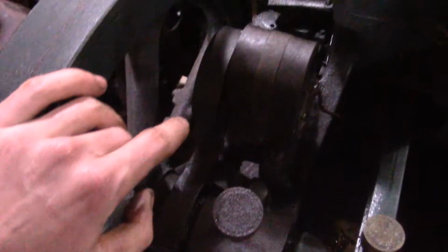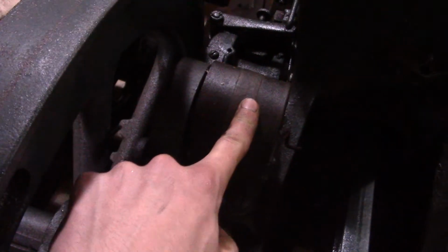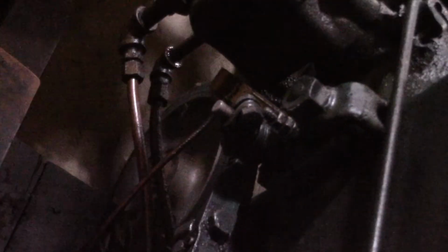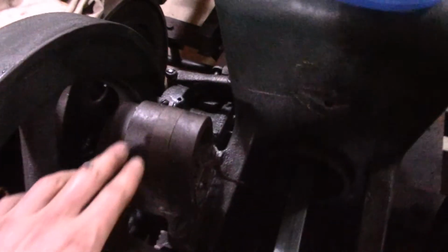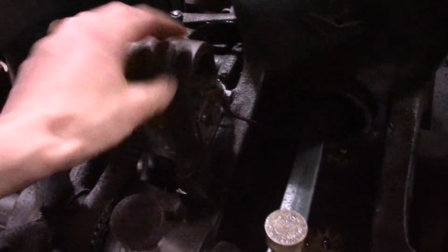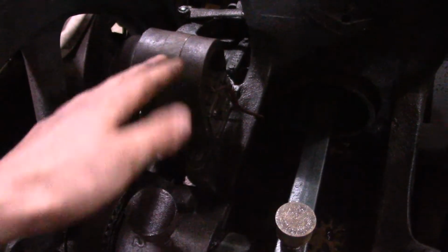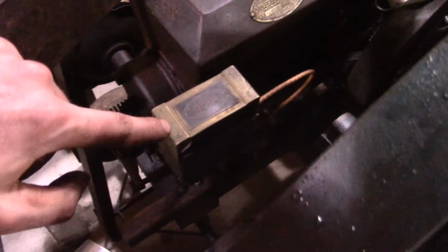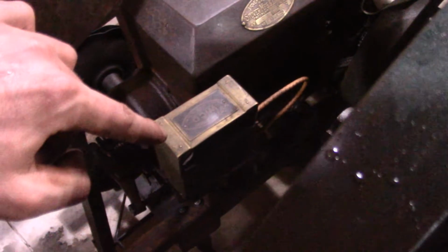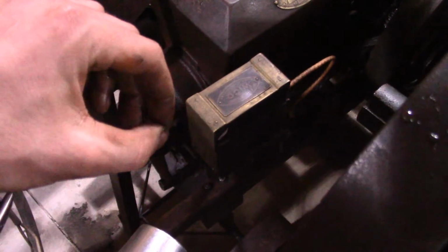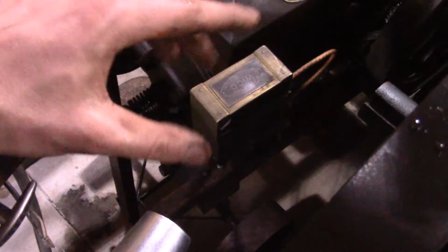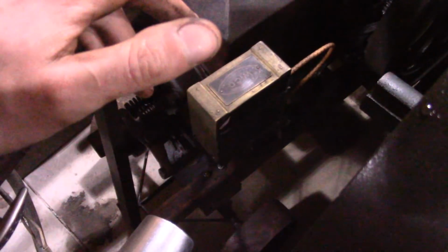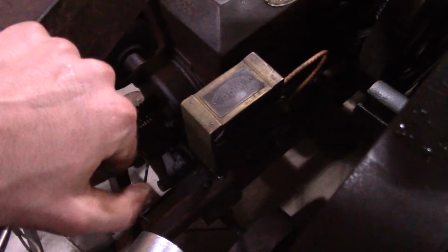Actually, now that I'm talking, I'm somewhat wrong. This is a low tension coil magneto. See, this engine also has points right there. So what this really is, is almost just a generator creating a constant 12 volts or so, and then when the points open and close, that will make a low tension spark. But anyway, this is a Wico EK. This is a high tension spark plug magneto, and it works that same way of using a moving magnetic field through a primary and secondary coil.